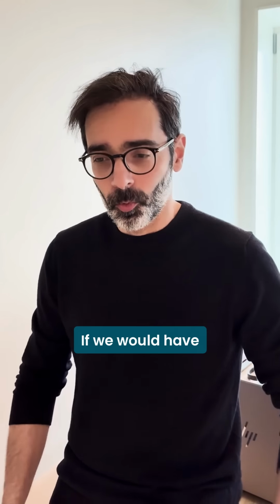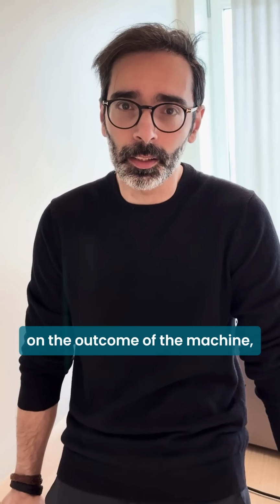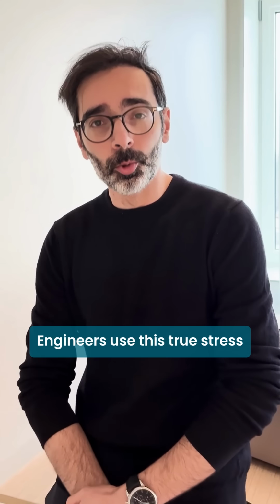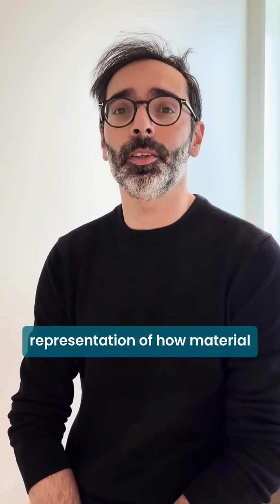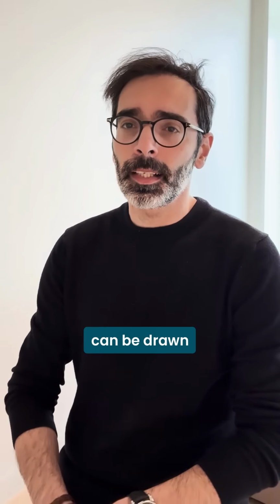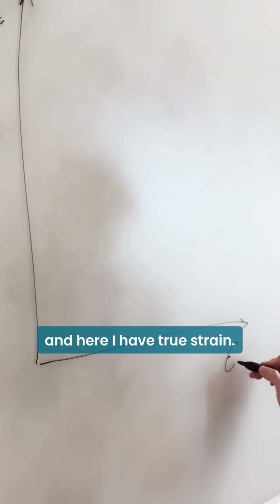If we put those samples into a tensile test machine and did a little bit of mathematical work on the outcome of the machine, we would get something called true stress, true strain curves. Engineers use these curves as a representation of how material behaves under stress. For mild steel, these curves, in a very simple form, can be drawn as something like this. Here I have true stress and here I have true strain.